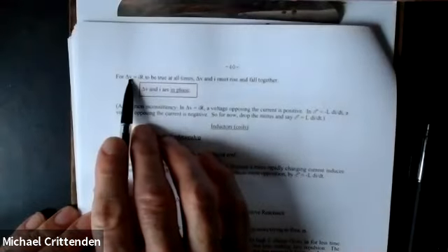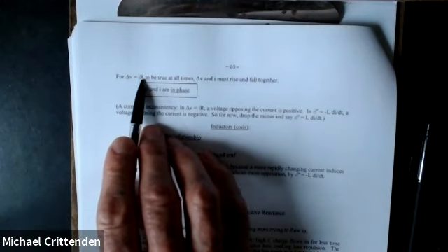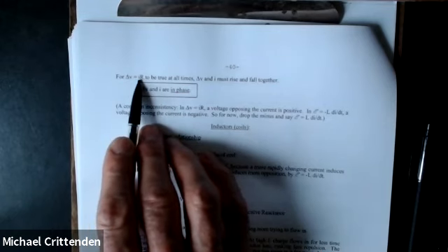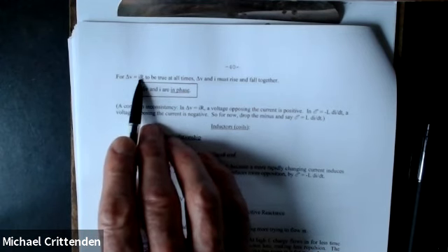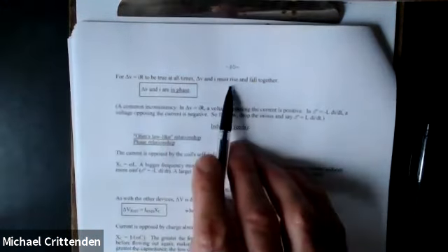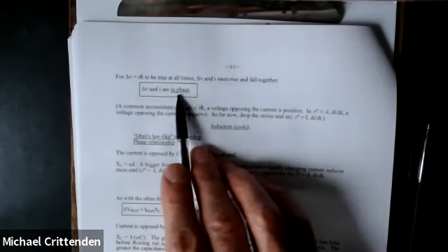In a resistor, the phase difference is zero, again, because of Ohm's law. The instantaneous voltage equals the instantaneous current times the resistance, which is just a constant. So if this gets twice as big, that has to get twice as big. If this gets 3 times smaller, that gets 3 times smaller. Whatever this does, this has to do the same thing in order for them to stay equal to each other. And so when this maxes out, this maxes out. When this goes through zero, this goes through zero. They rise and fall together. The voltage and the current are in phase.